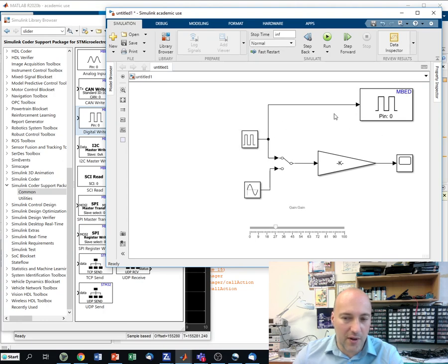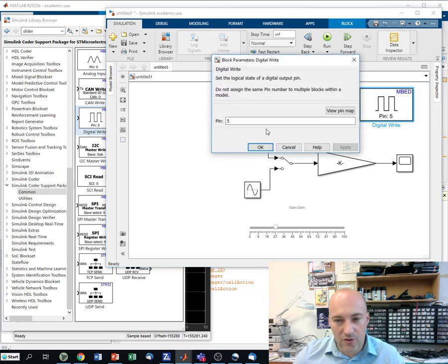It will be the blinking of the LED, and we'll see it on the real board. I will just configure this to the correct pin. So let me use, I don't know, maybe the red one, PB14. So let's set the red LED.